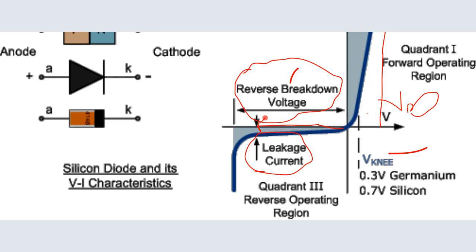If that voltage is pushed past that, then we say you've gone past the allowed reverse voltage. Therefore, the diode enters reverse breakdown, a process where the diode is no longer in control. In other words, the diode is no longer working. It cannot do the necessary thing.